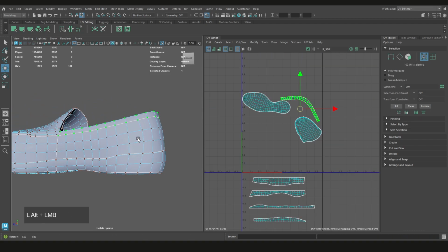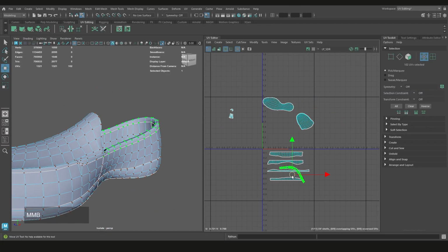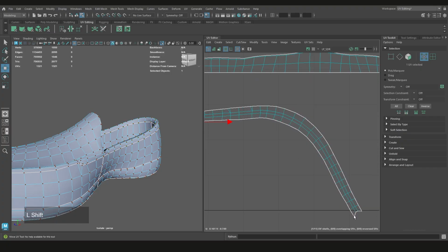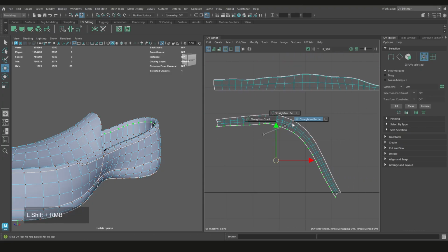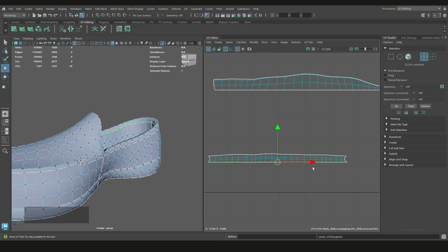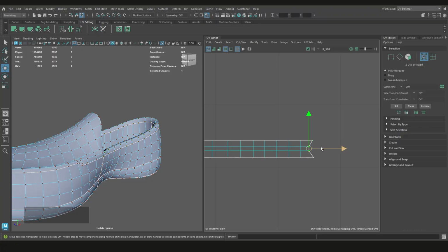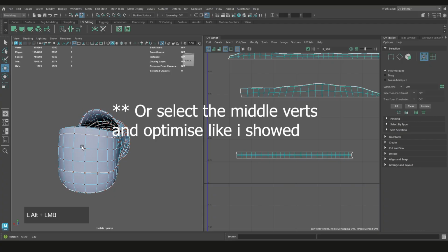Okay, and then this piece is over here, so that's not too bad. We can actually straighten this completely, now that I look at it. So I'm going to show you that one. Let's do from here to here to here. That didn't work. From here to here. There we go. And then from there to there. There we go. So we can go to straighten, sorry, straighten shell. There we go. And then let's see if we straighten UVs. This might not work. Oh, there we go. Okay, not too bad. And then you can either manually adjust this or there are ways of doing that, but that's honestly good enough. So we will leave it like that.